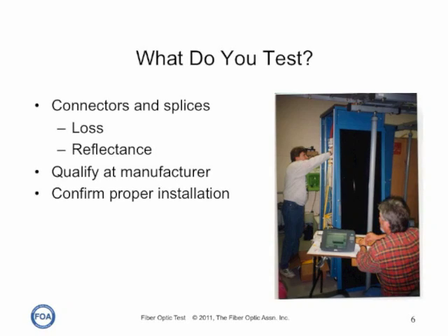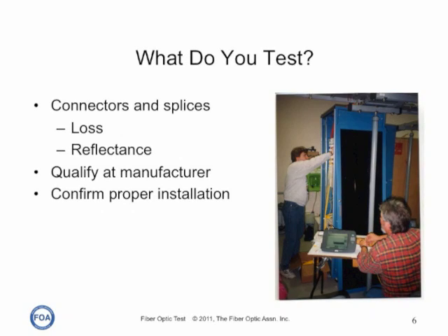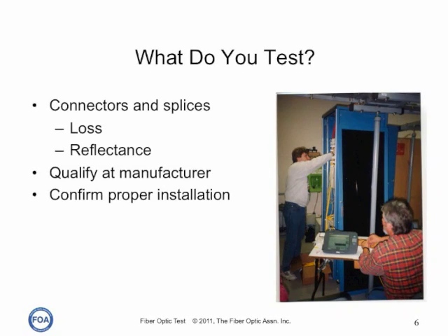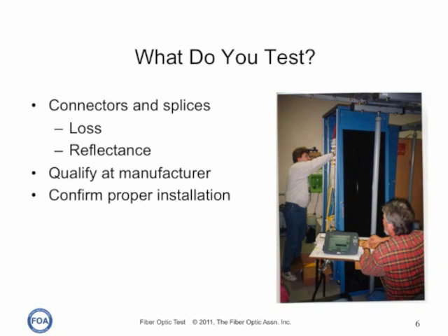Connectors and splices are qualified at the manufacturer. They will terminate many cables with their connectors to see what the average loss is when terminated in typical fashion. But the end user who's going to be putting these connectors on their cable plant will be testing in the field to confirm proper installation.